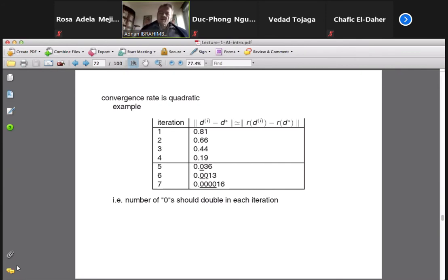When we started working with Electricité de France, this is one of the first things that I told them, of course, for the funding that they gave us in return: iterating to very small values is very important. Because if you're working with plasticity and damage and you're not iterating close to 0, you're accepting mistakes which are really not normal. Plasticity and damage are path-dependent procedures, so if you're not iterating, that means you're not solving the exact solution. You're actually solving a little bit on the side.